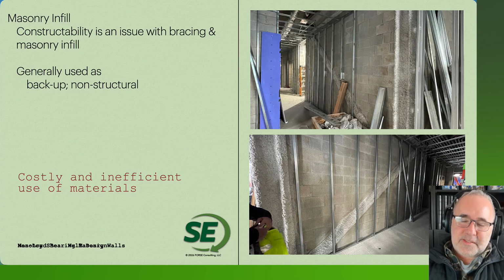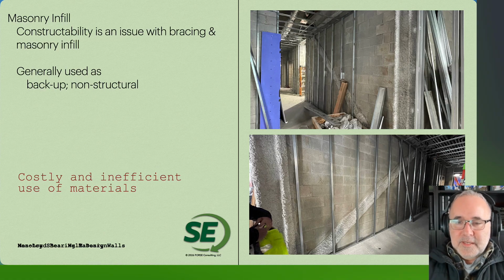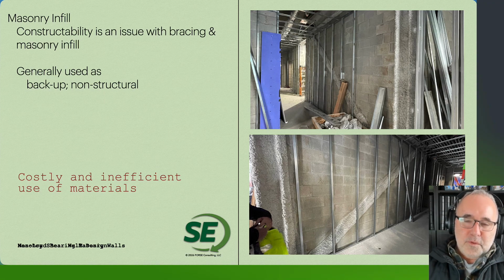But I would say about this, it's going to be a pretty inefficient use of materials. The masonry elements are going to be more expensive, having to cut and fit around a steel brace. The masonry elements are also going to be more rigid, so it's quite likely that they're going to take some of the stress that was meant for the steel brace because of the rigidity of the masonry elements and the overall gross area of those masonry elements. So oftentimes we see that this is going to be a more costly and less effective type of situation.